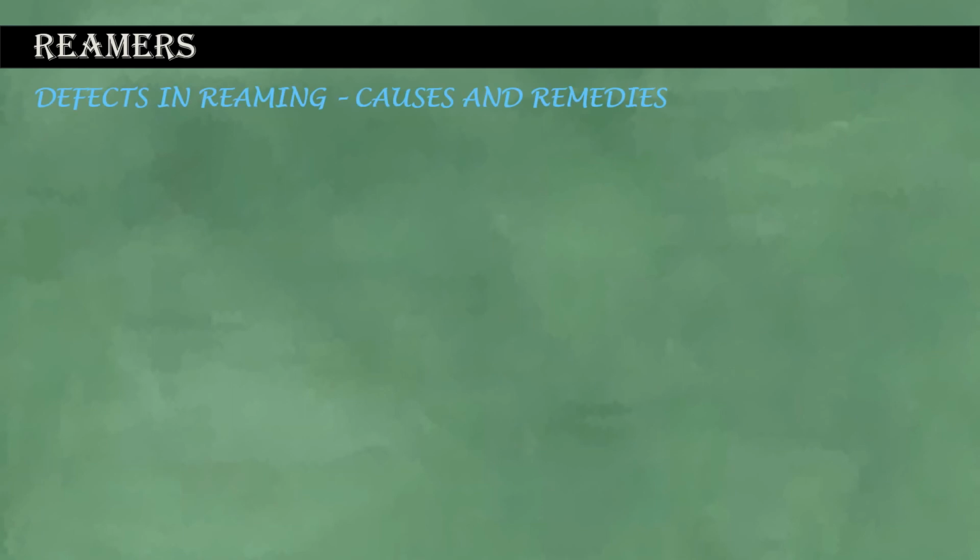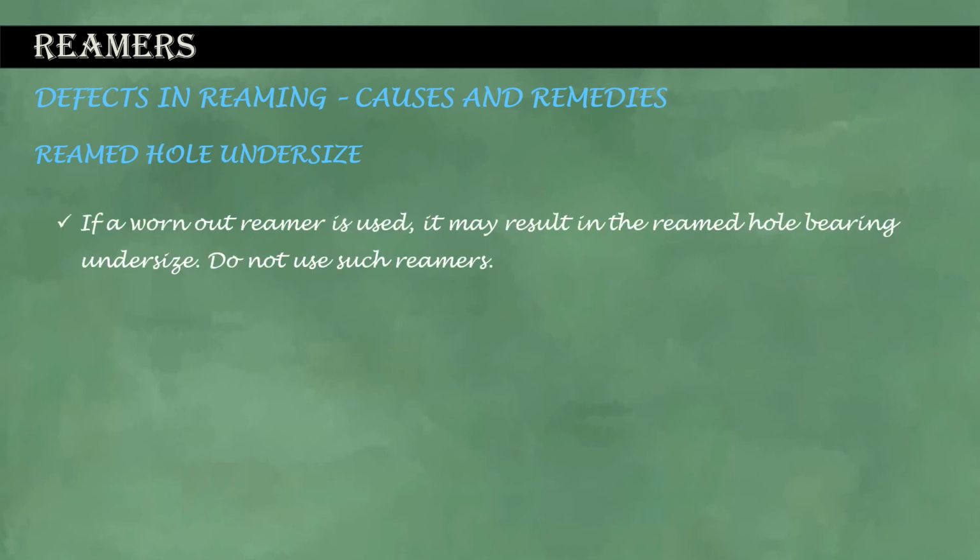Defects in reaming, causes and remedies. Reamed hole undersize. If a worn-out reamer is used, it may result in the reamed hole being undersize. Do not use such reamers. Always inspect the condition of the reamer before using.